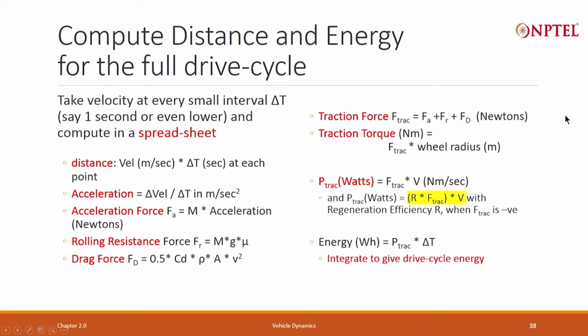All right. Now, if you notice in this, what I have not done is the slopes, because the Indian drive cycle does not define the slope, but in one of the assignment problems that I gave you, I actually included the slope. So, the spreadsheet will change a bit. We will include one more force called the force due to climb, or force due to gradient, and you have to add that and do the needful.